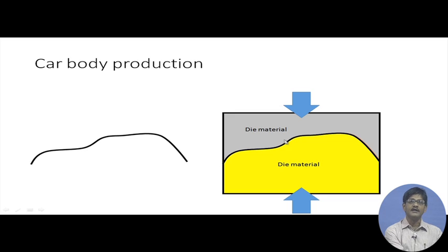If we plan to make these dies with the help of 3-dimensional machining, it is no doubt possible, but it will require a lot of expenditure because of tools. Tooling expenditure will be high, because if you have to cut strong, tough materials, tool wear will be high, and therefore expenditure for tooling will be quite high.